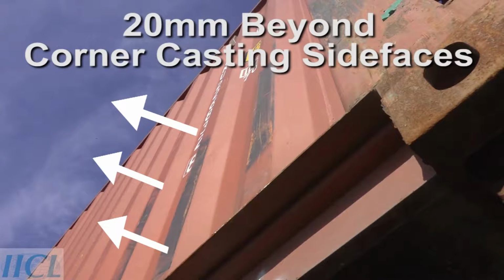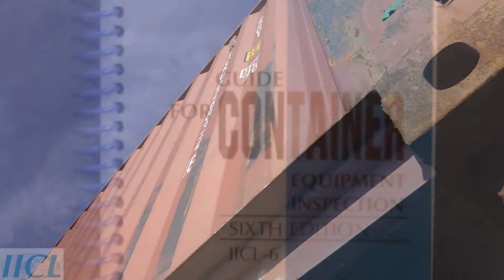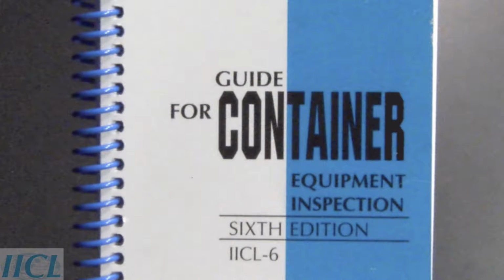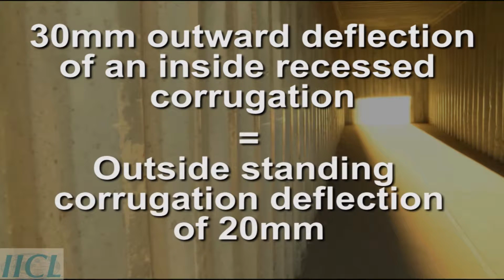The maximum side panel outward deflection allowed by the IICL is 20 millimeters beyond the plane of the corner casting side faces. As it is difficult to locate a virtual plane 20 millimeters beyond the corner castings and directly over the point of maximum deformation, the IICL uses the reference dimension measurement approach discussed earlier. For standard dry van container designs, a 30 millimeter outward deflection of an inside recessed corrugation is equal to an outside standing corrugation deflection of 20 millimeters beyond the corner castings.